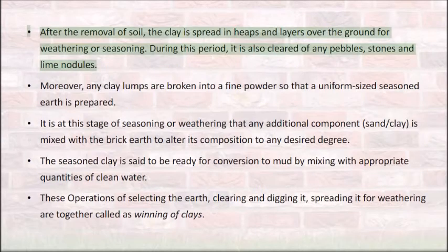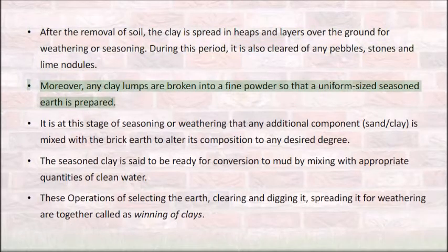After the removal of soil, the clay is spread in heaps and layers over the ground for weathering or seasoning. During this period, it is also cleared of any pebbles, stones and lime nodules. Moreover, any clay lumps are broken into a fine powder so that a uniform-sized seasoned earth is prepared.